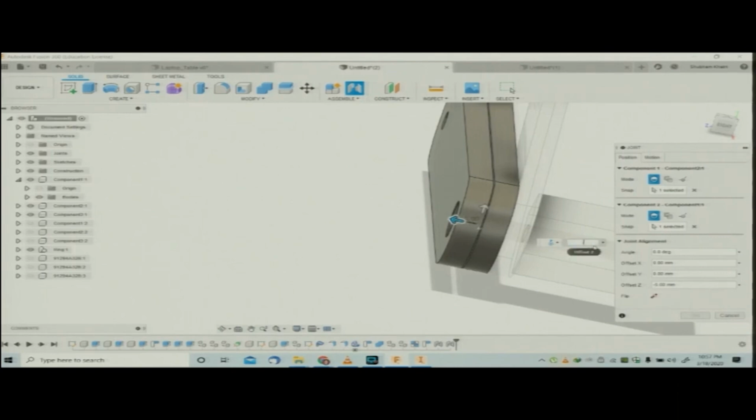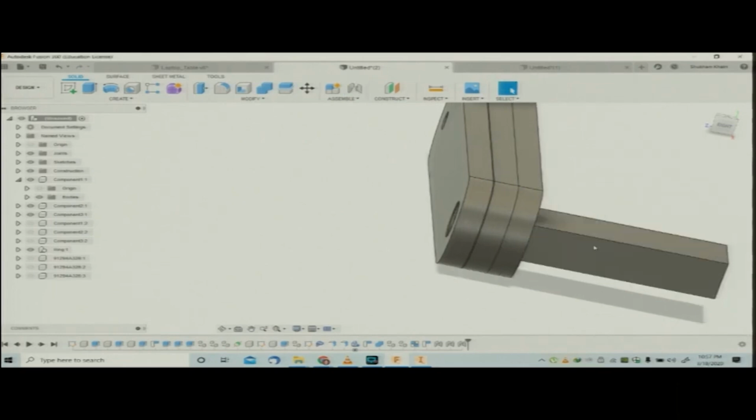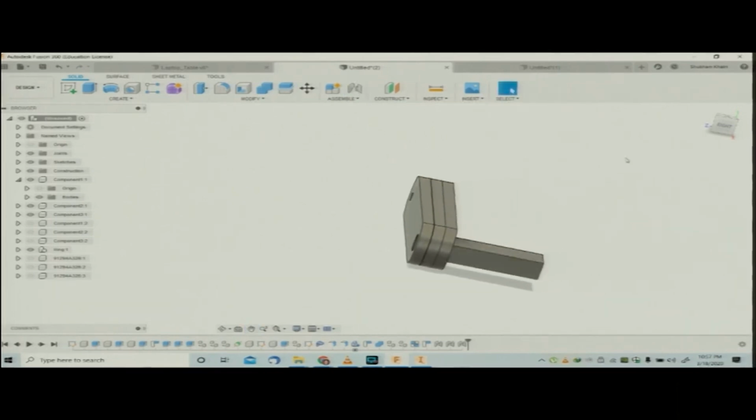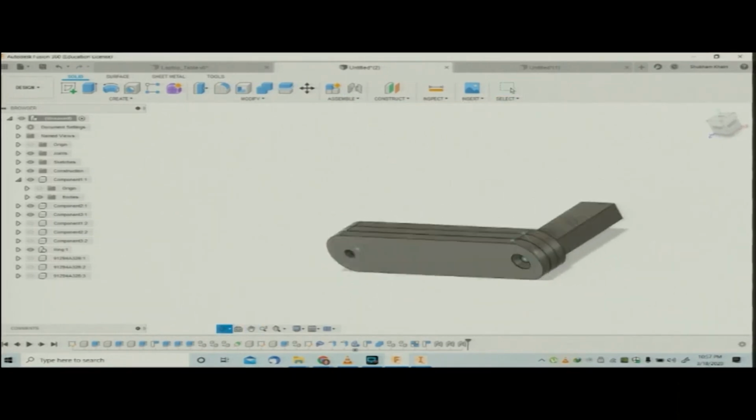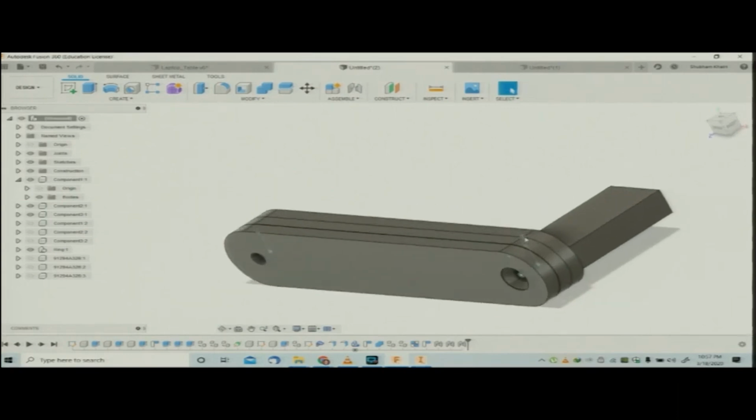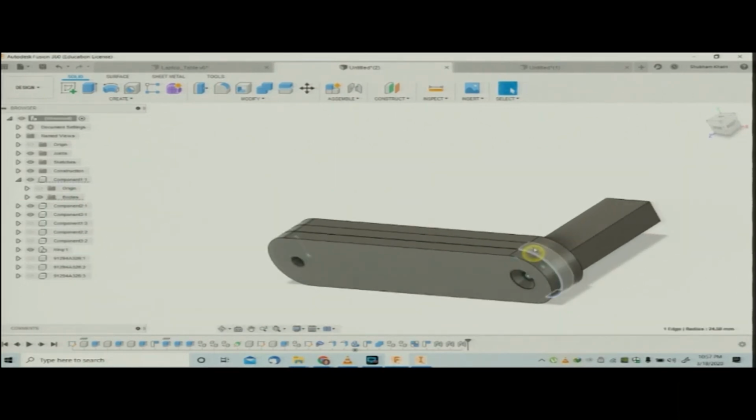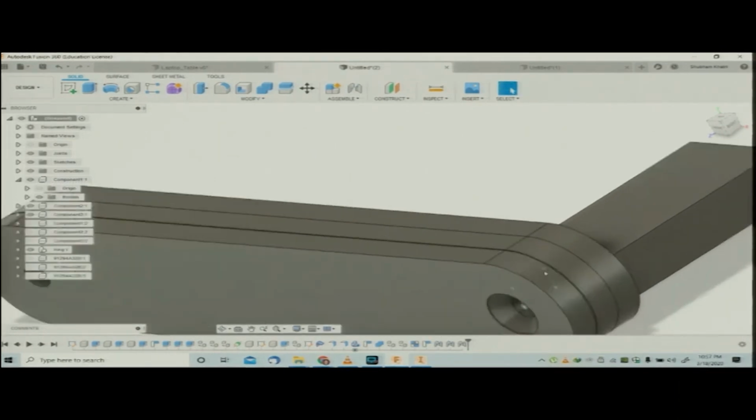Again providing the offset here. I provide epsilon to maybe minus 4.8. Okay. Now the whole revolution is almost ready. Now I need to provide constraints to this revolution so that the revolution is limited to some angle, maybe 45 degrees or 30 degrees for the hinge.